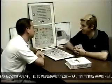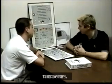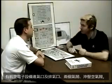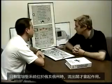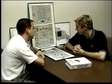As crazy as it sounds, my instructor told me this, and I have never forgotten it. There are valves that close. There's the avionics inlet and extract, the 2 pack valves, the ram air valve, and the outflow valve. The outflow valve only works if the pressurization system's in auto. Can you think of a time in normal operations that you might use the ditching switch? During de-icing.